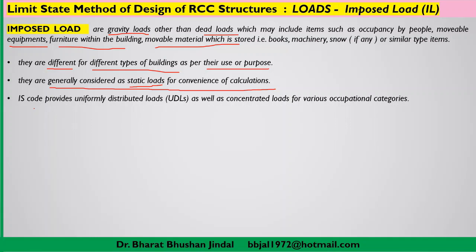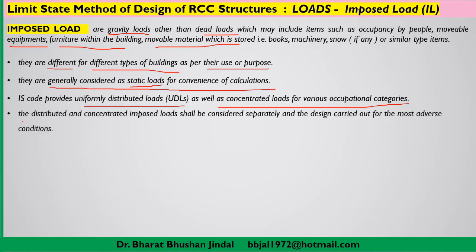Indian Standard Code provides uniformly distributed loads as well as concentrated load for various occupational categories. So you can refer to the Indian Standard Codes for various categories of loads. The distributed and concentrated imposed load shall be considered separately, and the design carried out for the most adverse conditions.